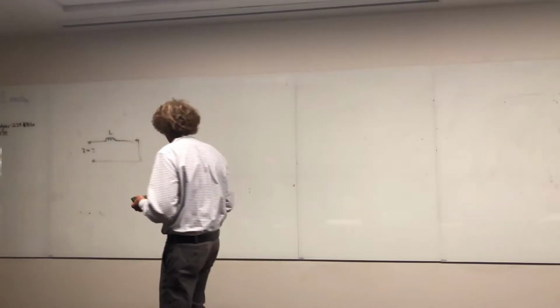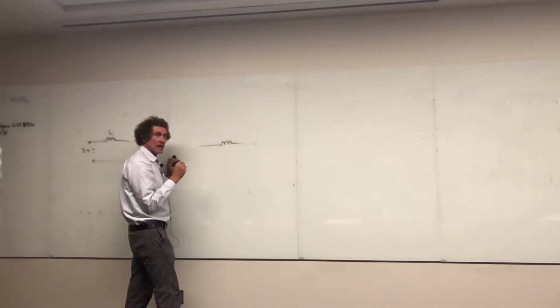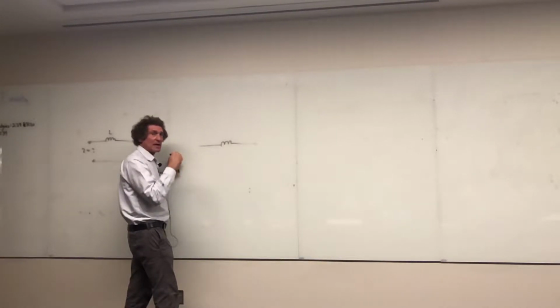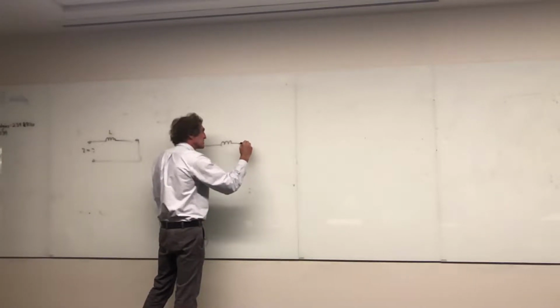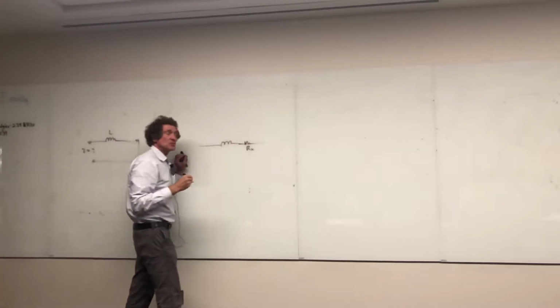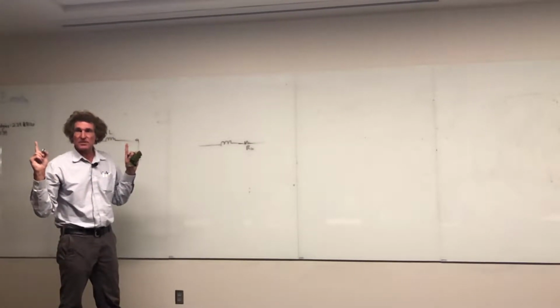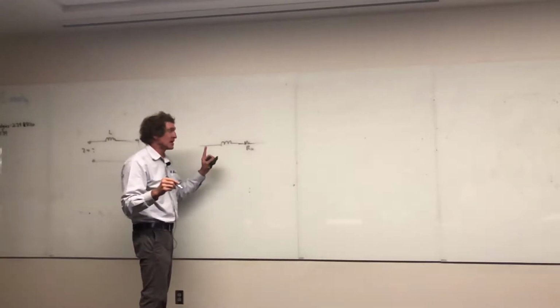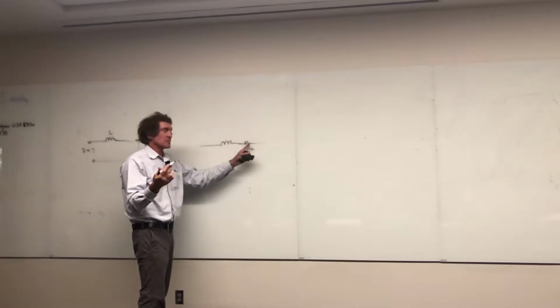So what does an inductor look like at high frequency? It always starts as a coil of wire, right? But within this coil, because there's a lot of wire, there's going to be a resistance. It's a parasitic resistance due to the length of the wire. The voltage developed across that inductor is not only because of the inductive energy, but also because of this resistance.